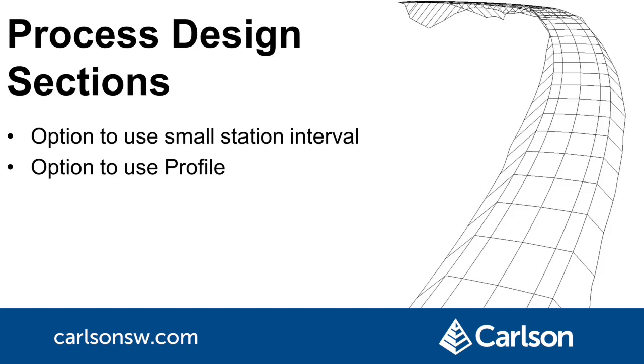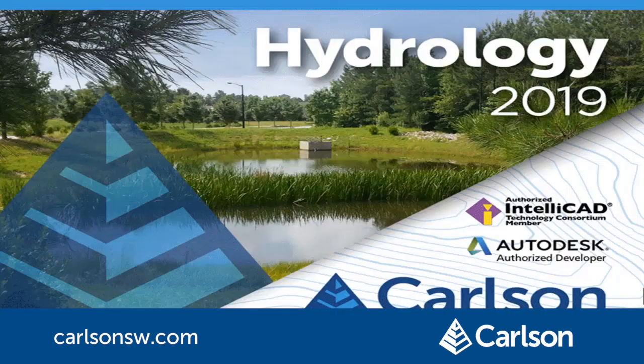Process design sections is for creating a road from cross-sections. Now the program has an option to interpolate stations at a smaller interval than the source sections. And there's a new option to use a profile to set the elevation for the interpolated stations. Next is Carlson Hydrology.